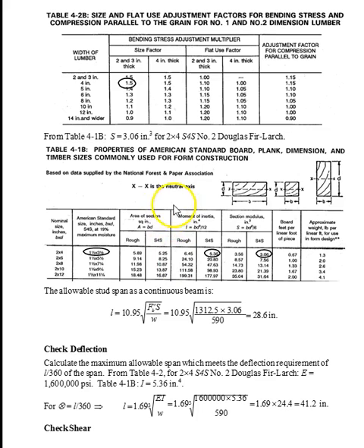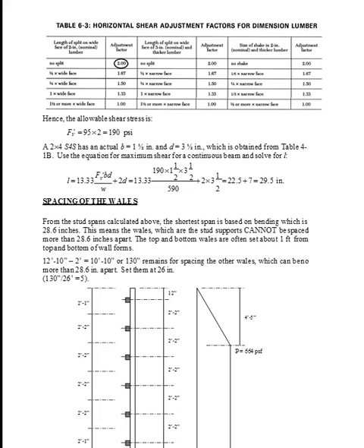Again, based upon different types of wood, the shape of the wood members, you're going to be able to do all of that. You can check deflection. Again, if you look at the programs, you'll see tabs that check all of these items. So what I'd recommend is that you go through tab by tab and look at those items. And I'll talk about that next week too, so we will do that together. Don't worry about it. I want you to think conceptually about what's going on right now. Again, you can change the spacing of the wales, just like you can change the spacing of the studs. You can also change the spacing when you're looking at horizontal on the joists.